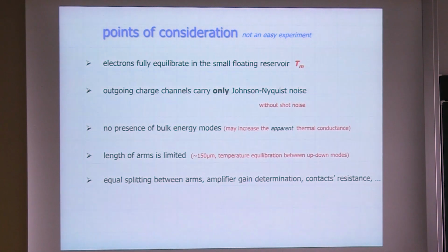But yes, we take care of that. Also, this is another important thing: we are measuring noise. So I cannot allow my device to have any other noises than the Johnson-Nyquist noise that I'm measuring. This I also verify. So, this device is faceted with all these multiple contacts because of that. First you check all these things, and if all the boxes are good, then only does it go to the next level that we measure. Okay?